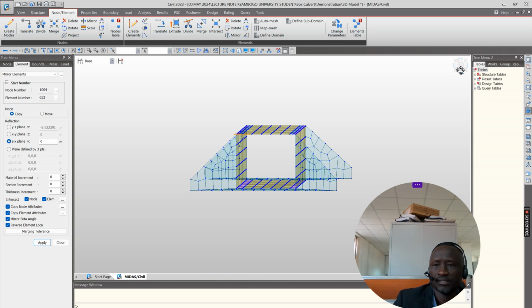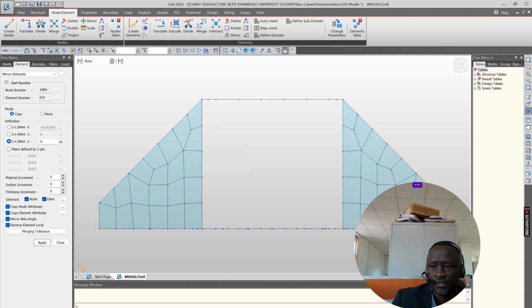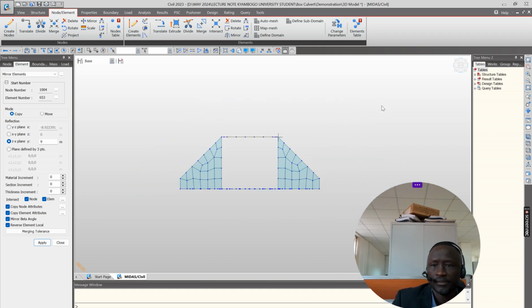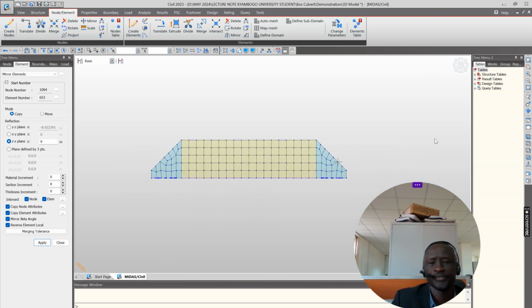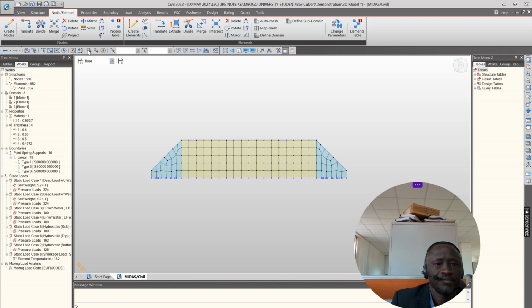The spring constant, I told you we shall learn more, is quickly the bearing capacity divided by the allowable settlement. Settlement ranges between 20 to 25 millimeters. So I would quickly go here and highlight that.